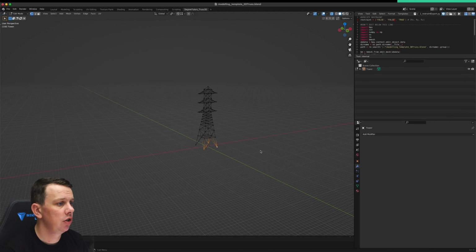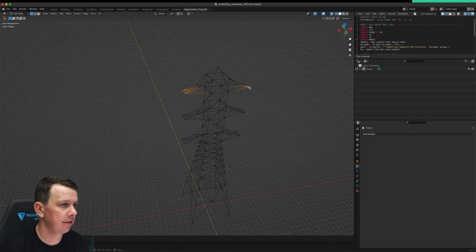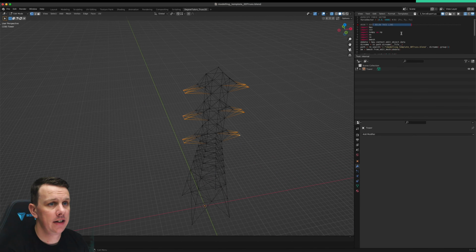The last thing we needed to do was to export some force data. I'm going to change them back to true in case I'm in here and I forget that I've done that. So I'll just leave them as true. So the next one is going to be the force data, right? Again, you just come in here and select the nodes that you want to have forces applied to. Here again, unless you want to dive into the code, ignore all this, you don't need it. All you need to do is edit these numbers here, right?